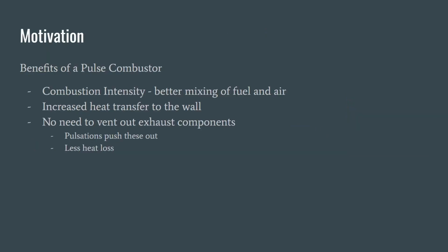So why do we even care about this? Pulse combustors actually have some benefits over a normal combustor. First of all, you have better mixing of fuel and air, which leads to more intense combustion. You are also able to transfer much more heat through the walls, as the otherwise present insulating layer of the tube is stripped away by the acoustic velocity, allowing much more heat transfer through the tube. And finally, the pulsations of the combustor will push out any exhaust components that in a normal combustor would have to be dealt with in some other way, making pulse combustors much more simple and privy to reduced heat loss.